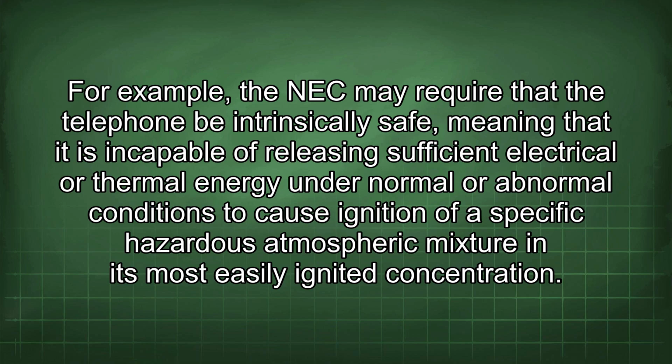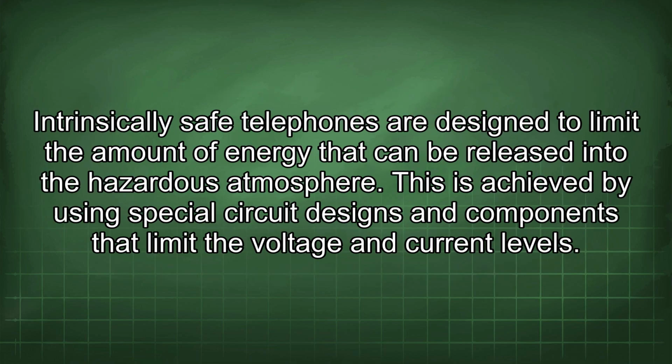For example, the NEC may require that the telephone be intrinsically safe, meaning that it is incapable of releasing sufficient electrical or thermal energy under normal or abnormal conditions to cause ignition of a specific hazardous atmospheric mixture in its most easily ignited concentration. Intrinsically safe telephones are designed to limit the amount of energy that can be released into the hazardous atmosphere. This is achieved by using special circuit designs and components that limit the voltage and current levels.